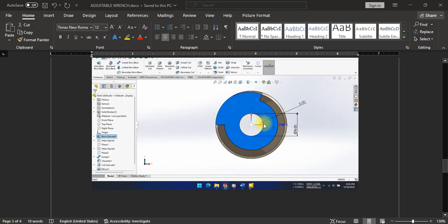and if you see the picture, we have a hole on this roller. The dimension of the hole inside is 8 millimeter, and we have a distance of 5 millimeter from the hole inside, and the outside is 5 millimeter. So if we want to create this sketch, we can create 2 circles, and after that we can define the inside circle as 8 millimeter. After that we can define the distance of the circle as 5 millimeter.